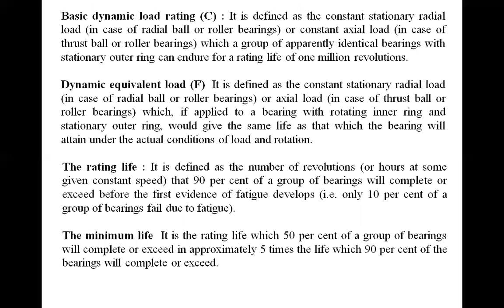Now just like static, there is a basic dynamic load. The basic dynamic load is the dynamic load condition, that means it is in the working condition. It is defined as the constant stationary radial load or axial load which a group of identical bearings with a stationary outer race can endure for the rated life of 1 million revolutions.